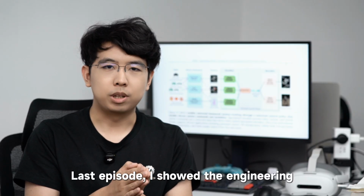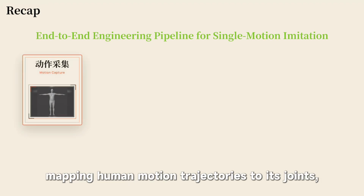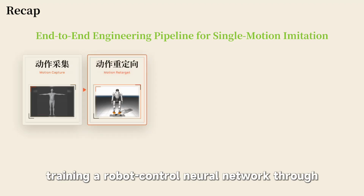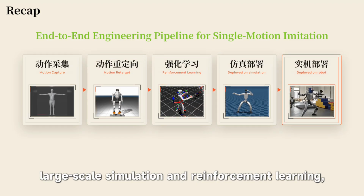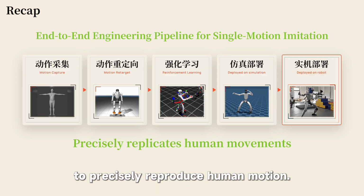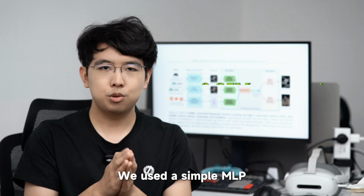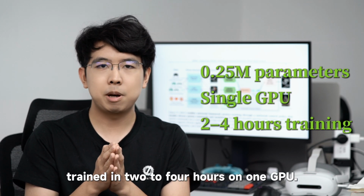Last episode, I showed the engineering pipeline for making a robot dance: mapping human motion trajectories to its joints, training a robot control neural network through large-scale simulation and reinforcement learning, then deploying it on the robot to precisely reproduce human motion. We used a simple MLP with only 250,000 weights, trained in 2 hours on one GPU.